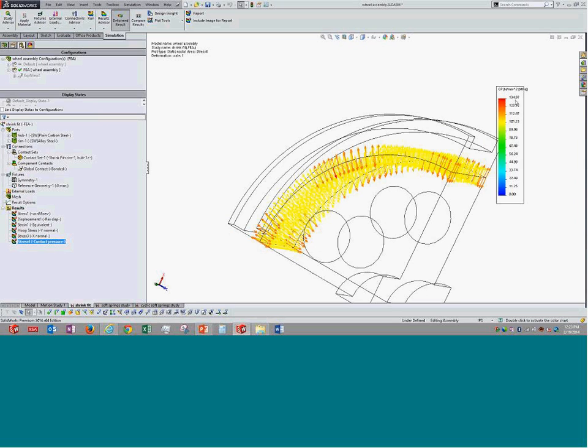If you see the contact pressure plot, the maximum pressure that we are seeing is around 134 megapascals. Therefore, we can multiply this by area, and we can know an approximate force that might be coming into this junction. The other kind of analysis, not done over here, is a non-linear or dynamic analysis, where we push the shaft into the bearing and see how much reaction force is required. That will tell you how much force is required for this shrink fit.